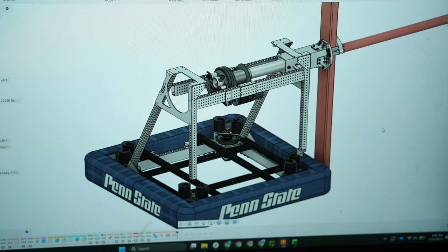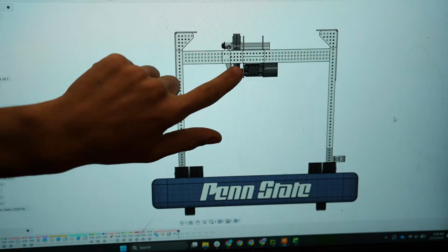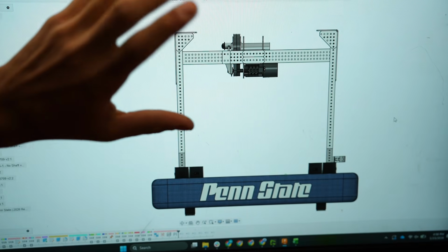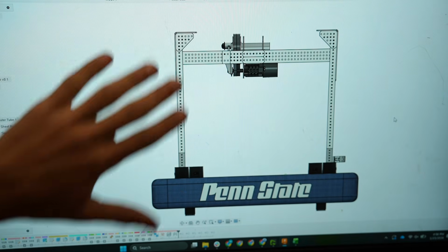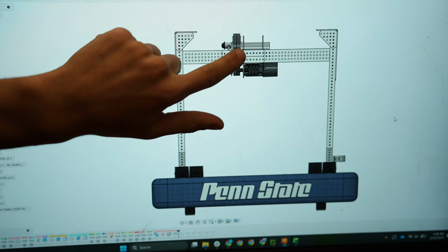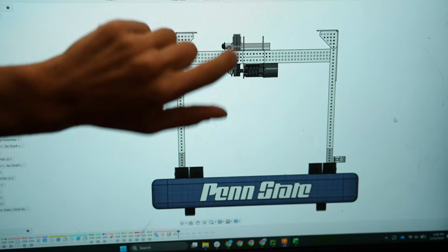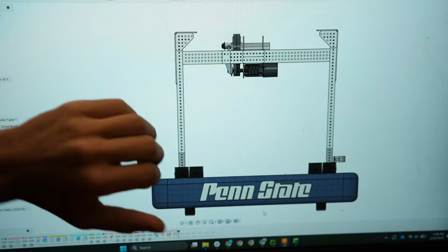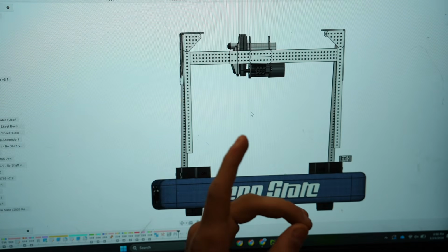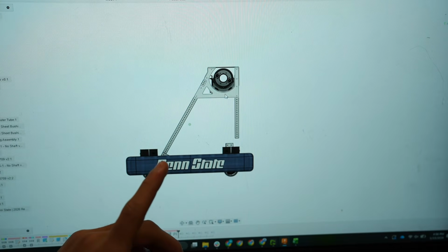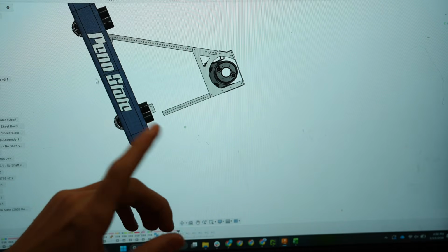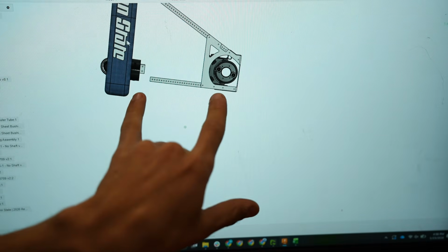We're starting with this because it's a little more comfortable to analyze than the pole. The forces are a little lower and the loads are simpler. As we look at this loading, we're analyzing the forces exerted from the climbing mechanism on the superstructure of the robot. There's going to be 150 pounds pure vertical in lifting from the bearing assembly or the torque assembly. Additionally, in the side direction, we're going to get a maximum load of 3,600 inch-pounds of torque.